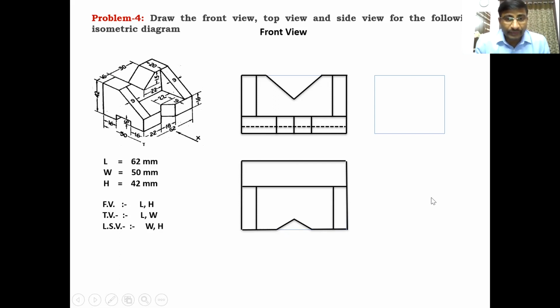Okay. And these inclined surfaces are also visible from the top side, which is a width of 9 mm on both sides. And draw two vertical lines in between these two horizontal lines. These vertical lines are at a distance of 16 mm from both sides. Another line is there, the line which is passing through this corner is also visible, which is a dark line.